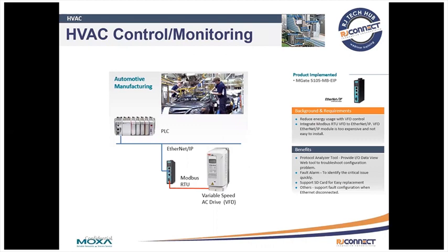An HVAC control and monitoring system where the customer needed to convert from Modbus RTU to Ethernet/IP, and they also needed the protocol analyzer tool to provide data view via the web tool, the fault alarm to identify critical issues quickly, the SD card for easy replacement, and support for fault configuration when Ethernet is disconnected as well.